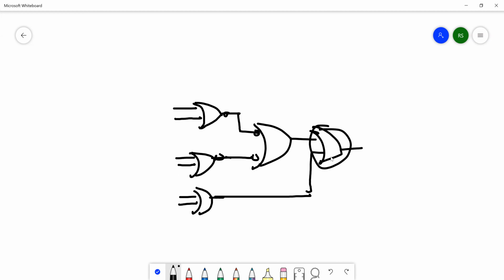But this gate will be stuck because there's nowhere to push. So that is going to create a problem for you. So as far as possible, in any of the examples or the numericals they ask, try to divide it into an even number of stages, 2, 4, like that. Okay, so this is in brief the method of bubble pushing, just a technique to improve the gate delay.